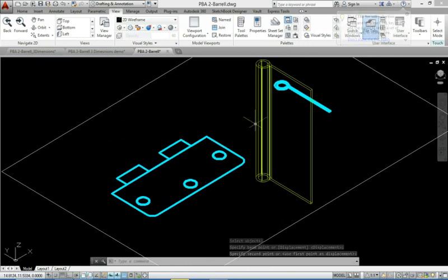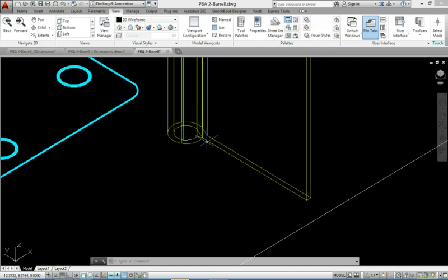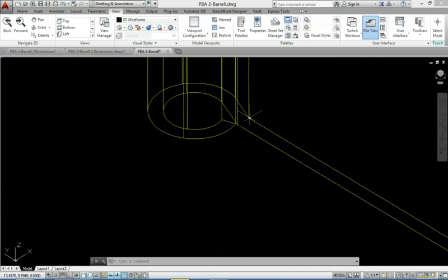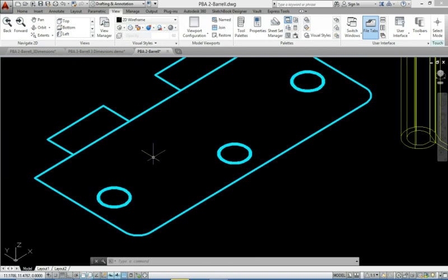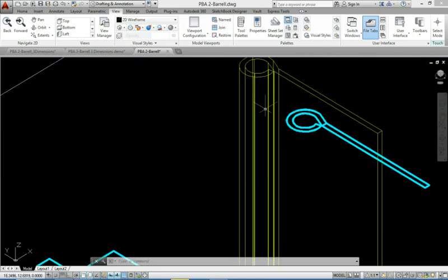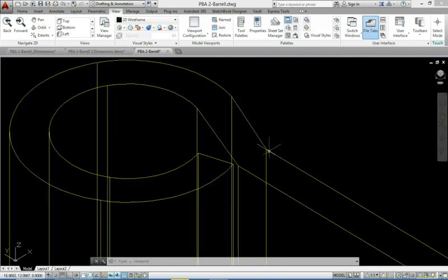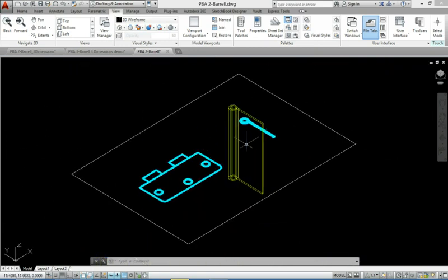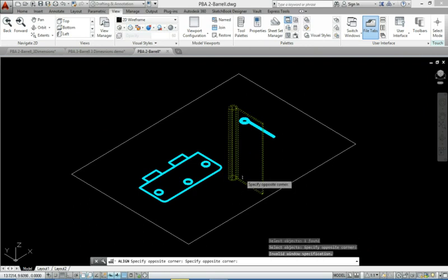Remember, this is our original two-dimensional object right here. The way the command works is it's asking you to move points from one place to another. We're going to move this corner here to here, and we're going to move this little corner here at the back to here. And then it'll rotate, move, and land in place. Align is spelled A-L-I-G-N. Select this object, hit enter.